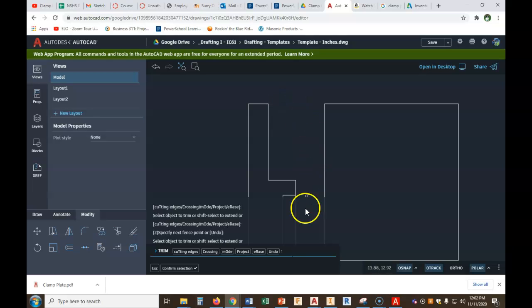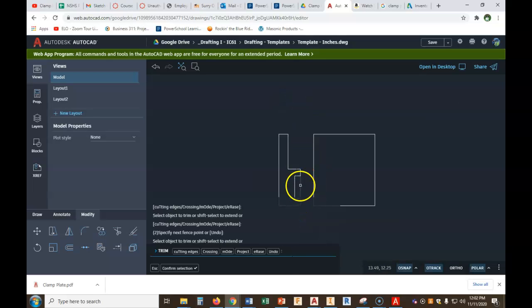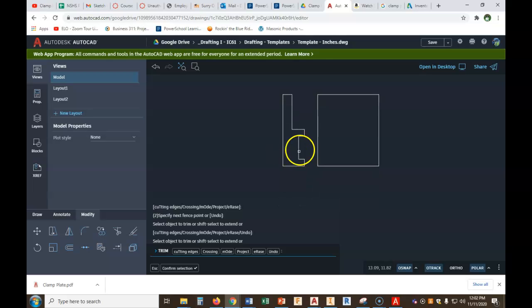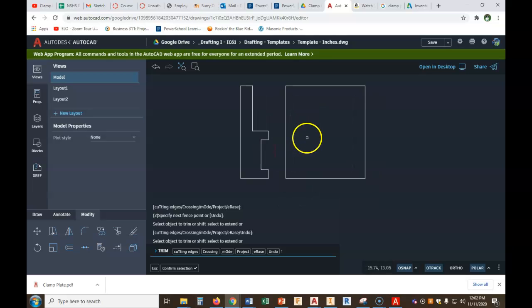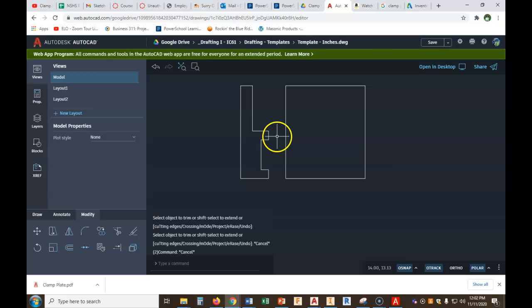There we go. And now I'm going to zoom out and get that one. So there we go. There's that shape. Okay? Now, remember, if it's a height in the front view, it's a height in the side view. So our overall height from there to there, notice it's the exact same here to here. But look, this platform from here up is a height. From here to here is a height. From here to here is a height.